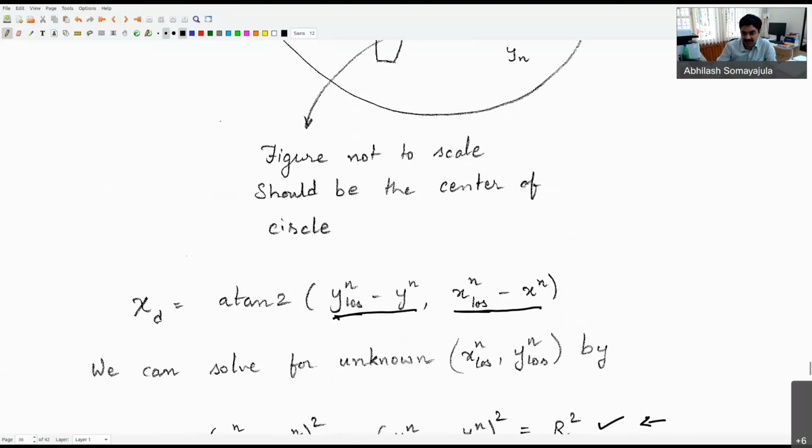Okay. Notice that this is slightly different as compared to the look-ahead distance-based LOS scheme, where we were primarily worried about what is happening to the cross-track error when we were specifying our course angle in terms of the cross-track error and the look-ahead distance. Here we are specifying it in terms of some given radius r, where the circle will intersect the two points. And then based on that, we are trying to position our vehicle in that direction.